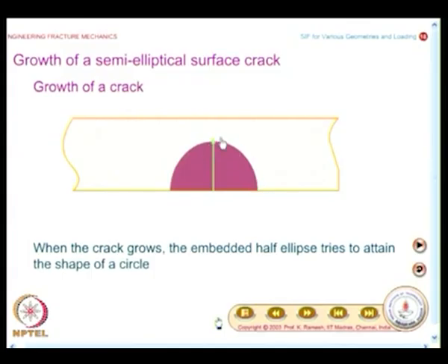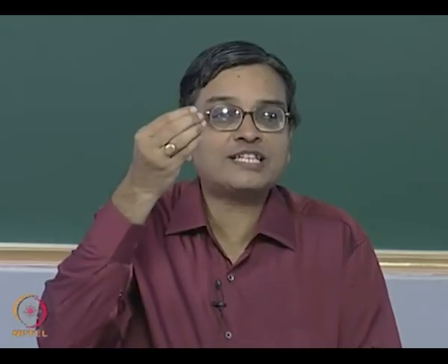and you have to note down many things in this. What we want is, if the crack grows like this and touches this surface, if I have a pressure vessel, the pressure vessel would start leaking. When it starts leaking, what can you do? First of all, you can go and find out something has gone wrong and you have to go and correct it. Other way of looking at it is, when the pressure vessel is leaking, automatically the loads acting on it come down. So, it is also a protection from that point of view. When the load acting on it comes down, it is good.